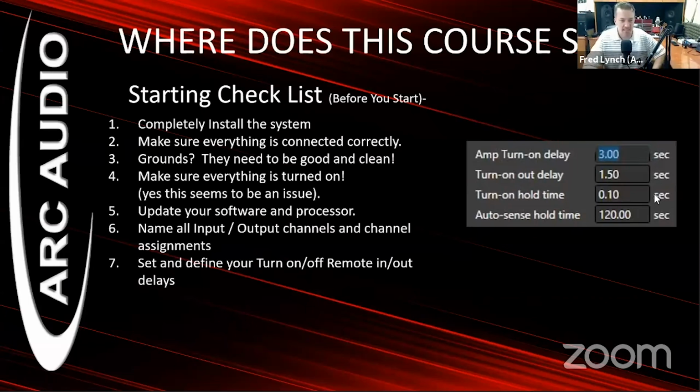The next step, of course, is set and define your turn on and off and remote in out delays. Now, if you look over on the right-hand side, amp turn on delay, this has been a little bit of confusion for some people. So amp turn on delay is only relative to a few products. That's the PS850, and that's also any of the ARC series amplifiers with the IPS 8.8 built into it. Now, what this does is this physically sets the delay for the turn on to any DSP equipped product that has an amplifier built into it. So if you put the IPS 8.8 into the ARC series, it'll control that amplifier only. If you're controlling the PS850, it'll control the amplifier section of that amplifier only.